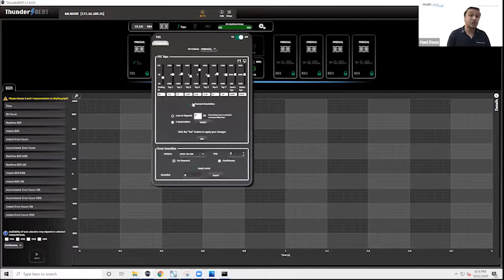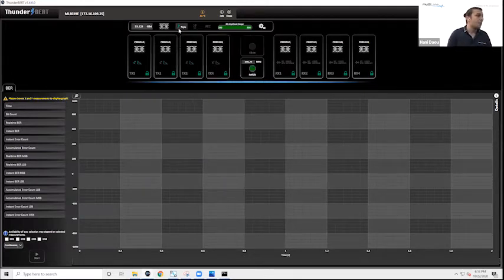And what I mean by that is channel emulation. I can go ahead and set any amount of dB loss I want in my channel. I can type it in here and select it, and it will actually set that amount of loss in the transmitter to emulate, let's say, a lossy electrical trace or a coupon board. But for my demo for setup 1, I'm going to stick in 3 taps mode.